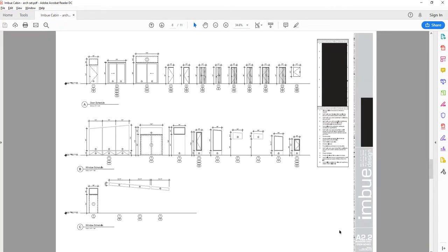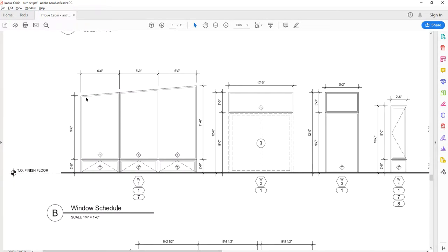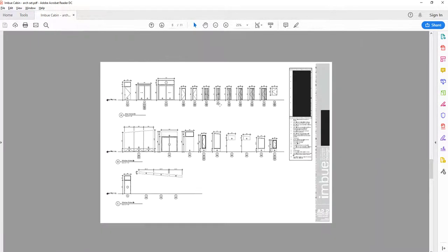Use this A2.2 window and door types to see how big these windows are and how tall they are. I think it's completely appropriate just to say for this window right here, we'll just do a square window. We'll encompass the whole thing, which means it's going to be 9'6" plus 2 foot. So that's 11'6". It's a big window, right? By 6 foot. So we'll have 3 of those, but don't worry about having this piece on the bottom and this piece on top and it angled. Just do kind of a rectangular one piece of window. Okay, I think that'll work just fine for this case.